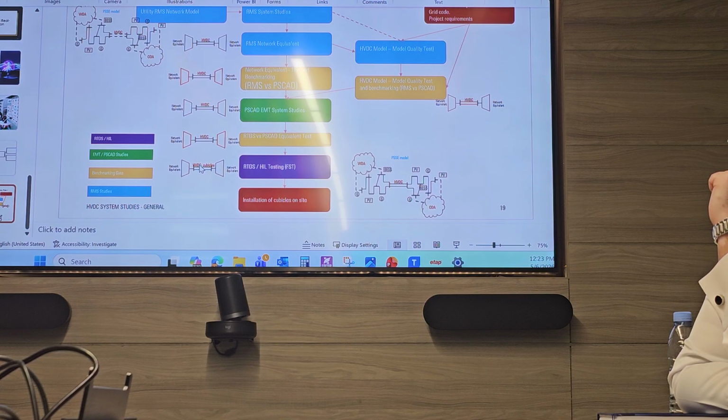Then in the software, we disconnect this and run simulations and say, okay, when this is disconnected, what if a fault happened here, there? If the study says you will disconnect the faulty cable or transformer, but power will still be there, the system will not be completely shut down, then you say, okay, now I'm good, and you arrange with the maintenance people, okay, next week you can go disconnect this.